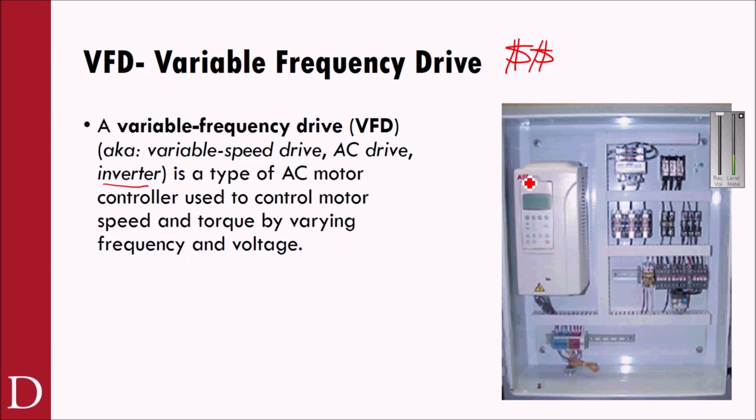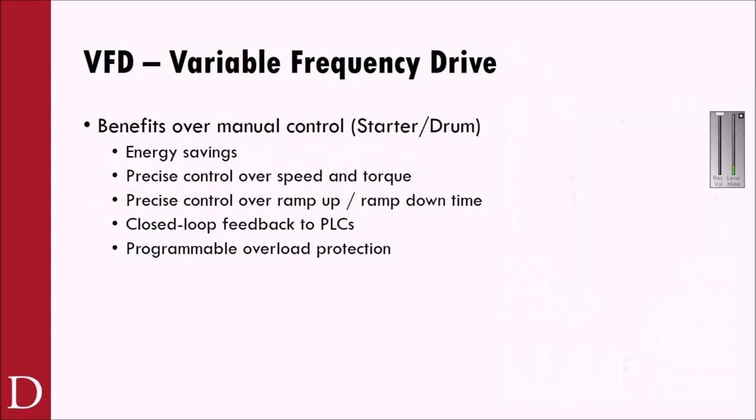This little control panel that you see on this VFD means I can control the motor from here. I can input all kinds of different parameters. I can do ramp up, ramp down time. I can do dynamic braking. I can do S-Curve functions. For the amount of features you get, the VFD is way cheaper than even a motor starter, just because you get so many features for maybe $200–300.